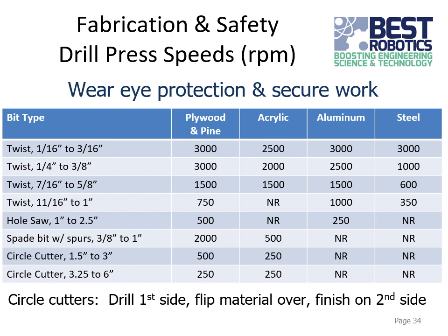The other thing here that's not really mentioned is that with some metals, at least the harder metals like steel, you're going to want to use some sort of cutting fluid. That's basically a lubricant that will keep the drill bit cool and keep it from overheating and deforming.